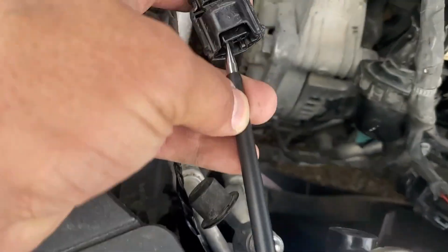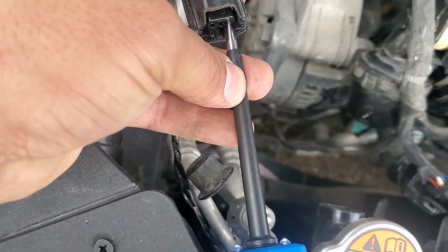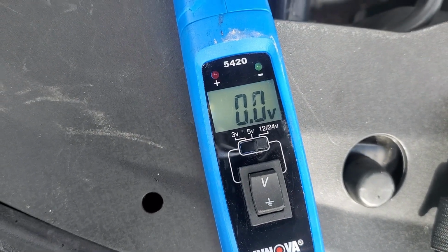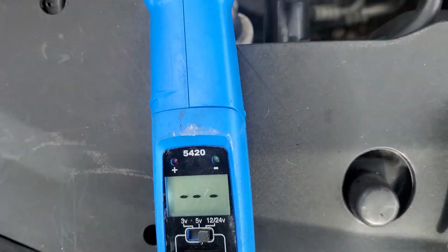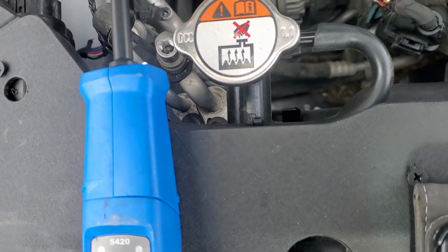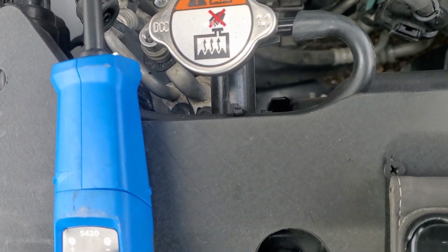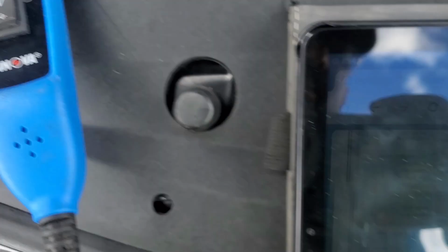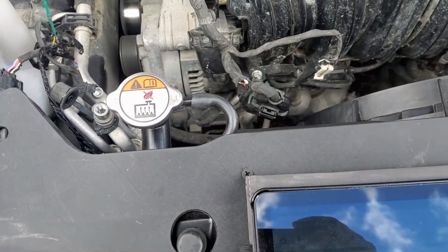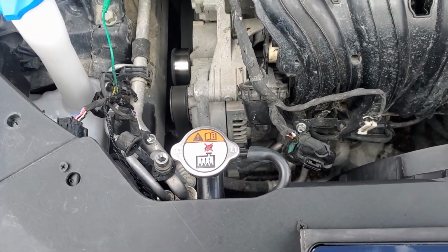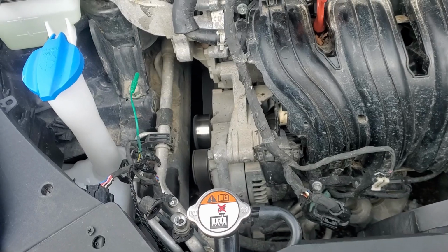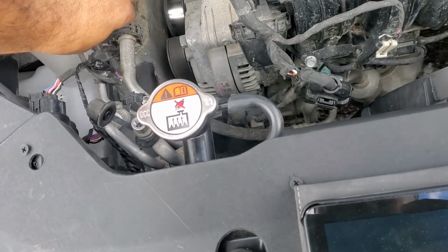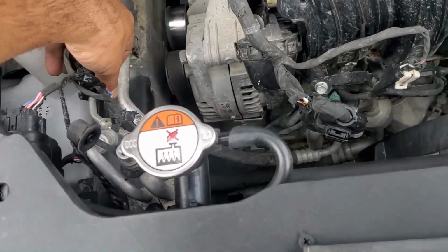So that yellow wire, we do have a ground. The white one, we have 5 volt. And the middle one, nothing, because it's the signal. This one has to be plugged in order to check the middle one. Let me plug it and go get my probe. Main one, we have 1 volt, as it showed on the scanner. In the test, it was showing 1.7, goes down to about 1.4, the voltage.